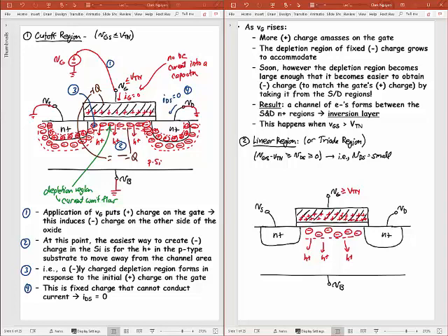Okay, because I put more voltage up there, I need more negative charge there. But at a certain voltage, explicitly this VTN, what happens is these holes are getting farther away. So the fields of my positive charge, going from positive to negative charge, are very weak out here. As that distance grows, it becomes harder to push holes away in order to get that negative charge.